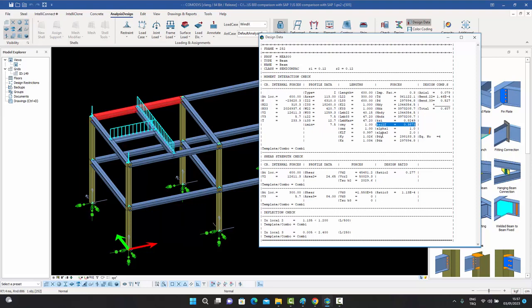These are all related to the buckling coefficients. PDY, PDZ, all these values are then used in the basic axial, bending 2-2 and bending 3-3 components of the total design stress. So this is 0.607, which would be less than 1, and so basically it's satisfying the condition.